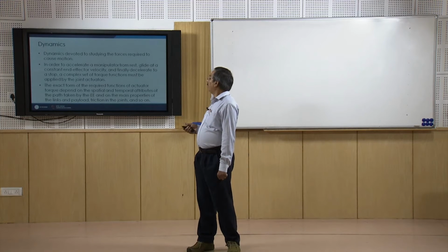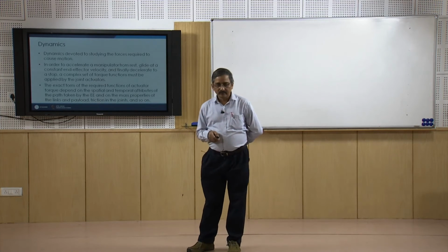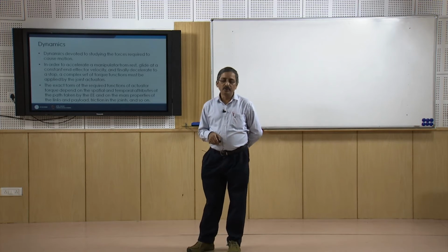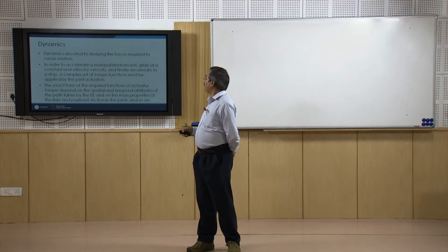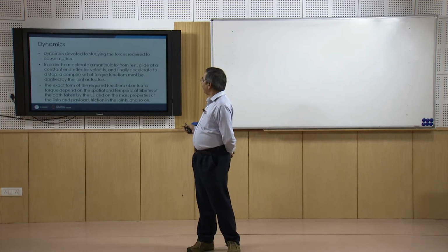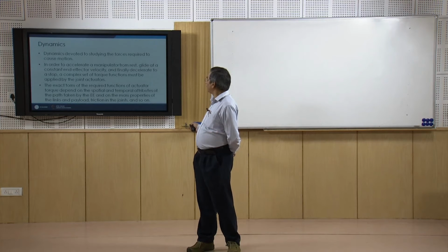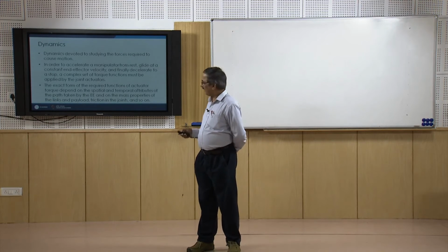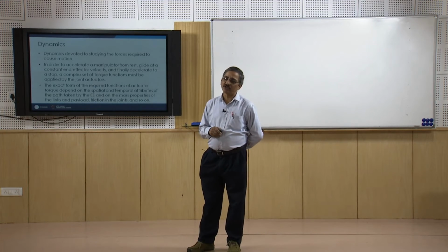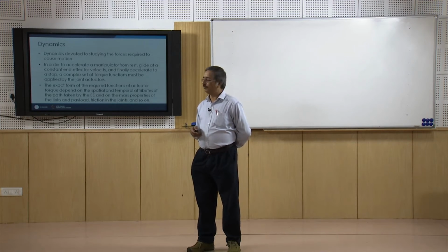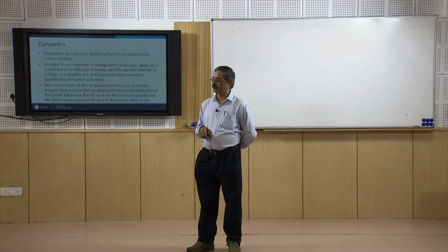As all of you know, dynamics involves studying the forces required to cause the motion. In order to accelerate a manipulator, say from rest, glide at a constant end effector velocity and finally decelerate to a stop, a complex set of torque functions must be applied by the joint actuators. Then only this type of motion of the end effector is possible.